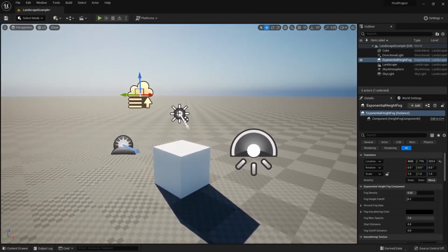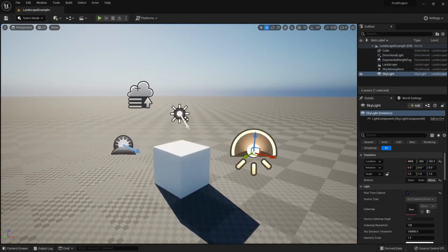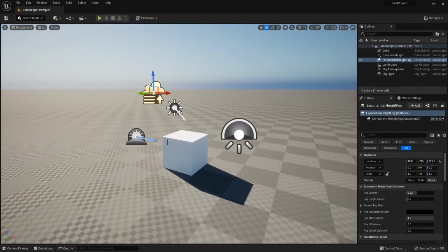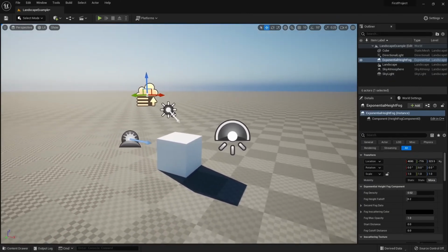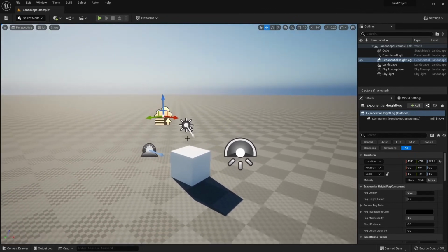And with that, a directional light, sky and atmosphere, skylight, and fog is pretty much how you light 90% of open world scenes in Unreal Engine 5. It is literally that easy. And what's amazing is that all these objects interact with each other successfully.